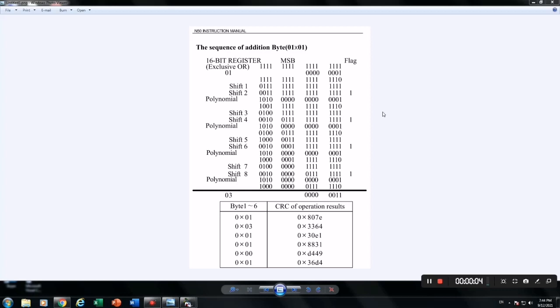Let me look at the Modbus industrial protocol CRC generation. For correctly sending a frame of command like this, and this frame is used for monitoring frequency from the inverter, we should follow this rule to produce the CRC bytes. This rule is the Modbus CRC method. To ensure that all of these bytes will be received by the inverter correctly, we should use an industrial protocol such as Profibus, Profinet, CANopen, or Modbus.